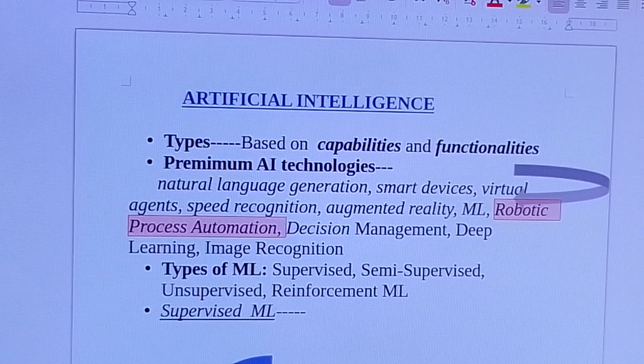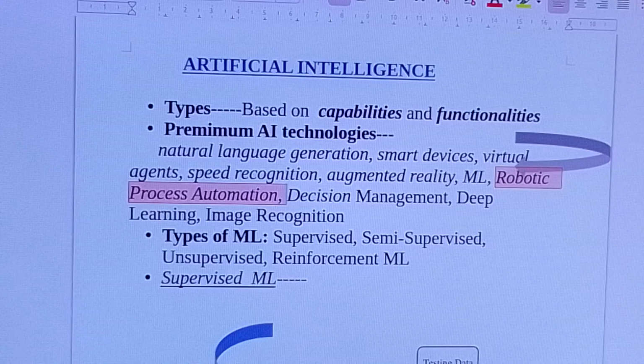Now, non-tactile sensors detect and measure magnetic fields, infrared and ultraviolet light, X-rays, electrical fields, ultrasonic sound waves or electromagnetic waves. Typically, non-contact sensors include electro-optical imaging sensors, proximity sensors, and range imaging sensors. Now, imaging sensors may use a laser scanner. Computer vision uses artificial intelligence, AI, to determine cause and effect phenomena to detect the fault or minimize their effects. Vision robots acquire knowledge about the environment by the interpreting, generating, and reasoning components.